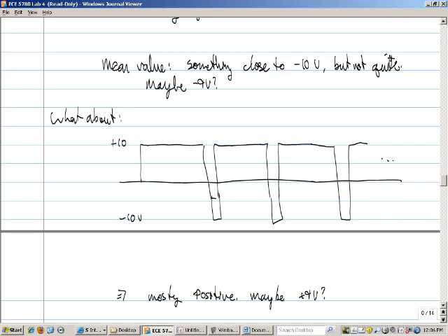If we have as many positive as we have negative, that's a 50% duty cycle wave. If we have all but one of them be positive and only one of them be negative, that's what we have with this wave right here, where we have changed the average value of this wave to be as positive as we can. We can't just let them all sit positive because then we don't have a square wave anymore.